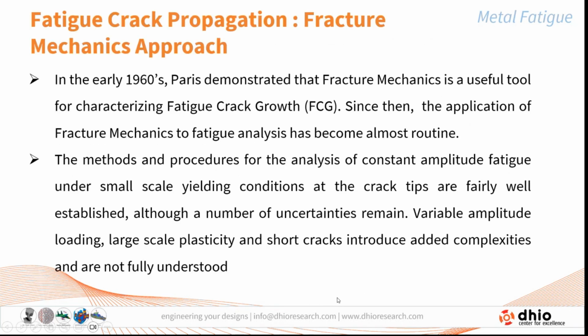Then the fracture mechanics approach is for crack growth, because Paris was the first person who introduced fracture mechanics and found it to be a useful tool for fatigue crack growth. Since then, this fracture mechanics approach has been used to analyze the fatigue life of a component.